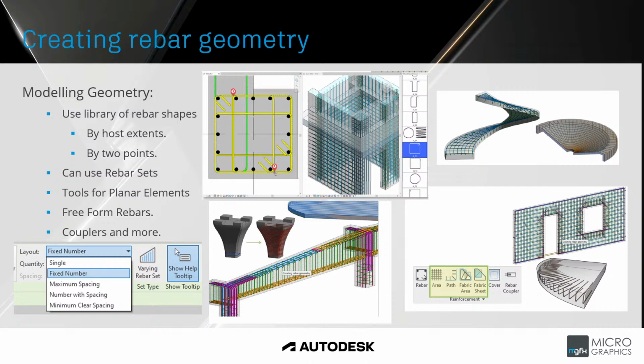Right, so on the right hand side we've also got tools for planar placing of rebar. So if you've got a concrete floor, concrete wall, or whatever, you can actually either have an area based rebar, where you can place those bars at the top and the bottom of a floor perhaps, or a foundation, and also you can have path rebar.